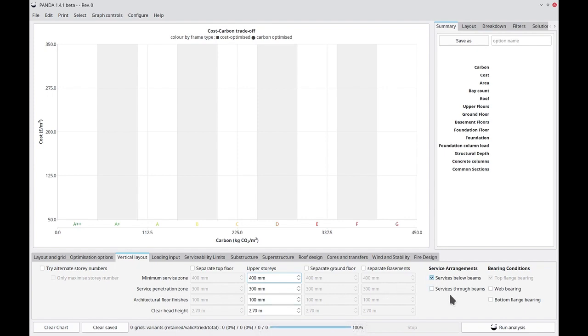And importantly, you may try to improve that by allowing more detail options on your beams. For example, steel beams could have little shelves on the web, allowing the beam to go into the decking, or bottom flange bearing, that is your slim deck kind of arrangement, where the decking is held by the bottom of the beam.